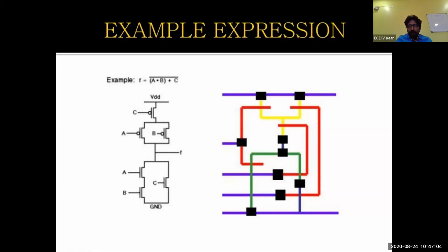And then for this dot operator, there is another input operator, that is plus C. Even to recognize how many PMOS or NMOS we need, it depends upon the number of variables given here. So here there are three variables. It means that we require 3 PMOS and also 3 NMOS.